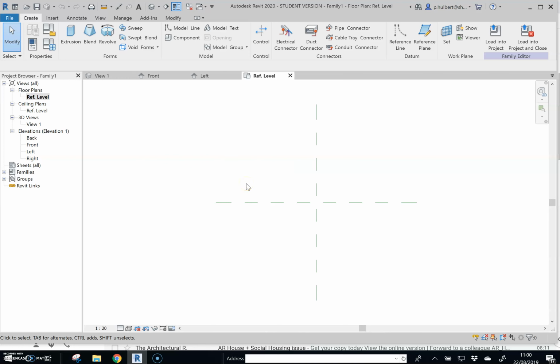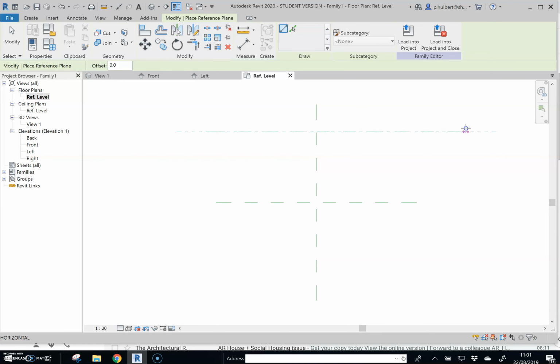So we've got a brief to build a house, and it has plan dimensions of 8 meters by 5 meters. So you're not quite sure what scale you're working at. The viewpoint, you've got scale here, but this is all being drawn effectively in 1:1 at this stage. There's a tool here called a reference plane where you can strike new lines across this in order to create new shapes. So if we do create and then reference plane and then just drag with your mouse across here,